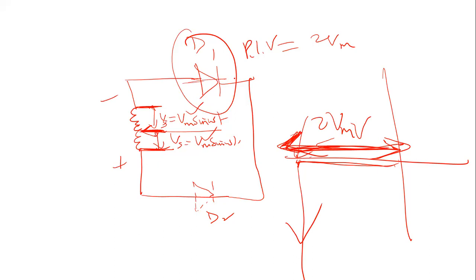It will burn because of the large quantity of free electrons generated under the avalanche process. Once you generate a large quantity of free electrons, a large current will pass through it, generating lots of heat across the p-n junction, and the heat will completely destroy your p-n junction diode.